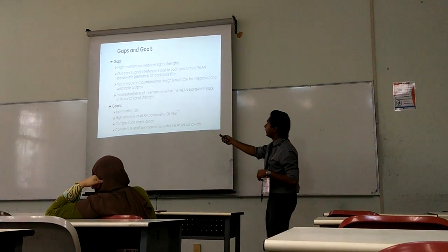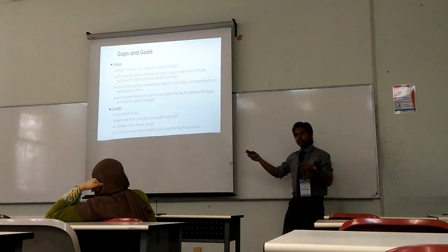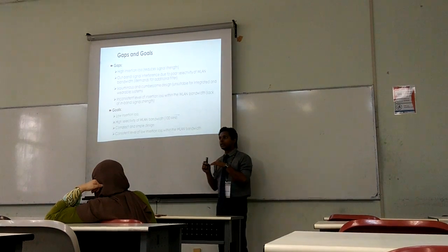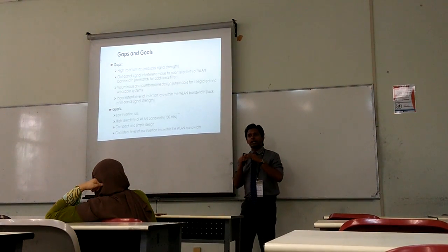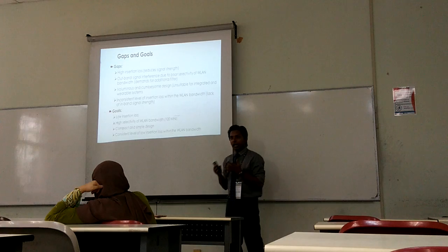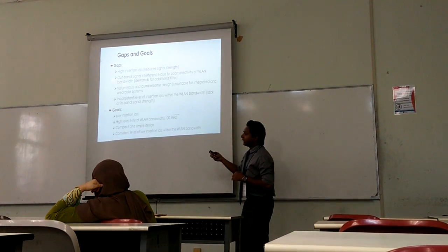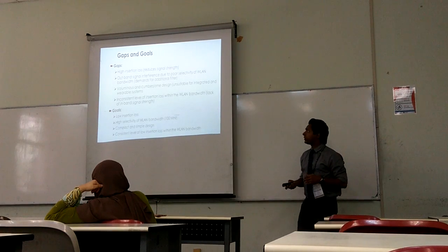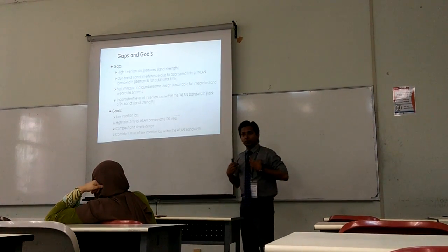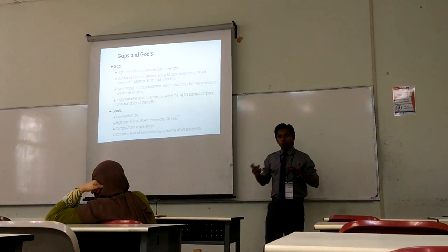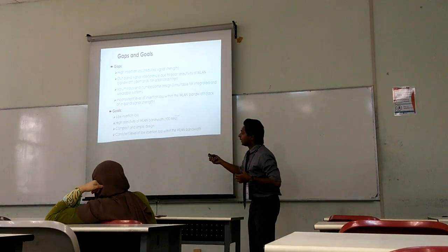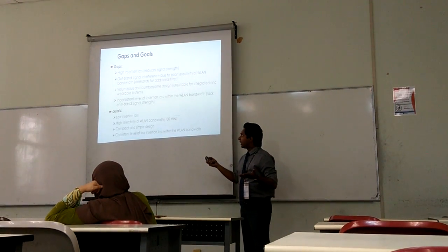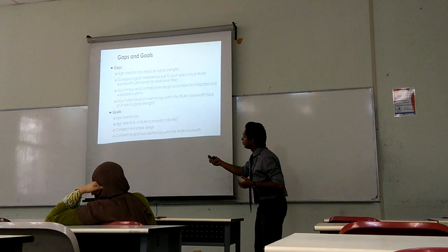Also, the filters are voluminous and cumbersome in design. As I said, the fragmented structure or the defected ground structure are difficult to design and implement. And also, some filters are voluminous, which is unsuitable for integrated systems, or these days, for wearable systems. We are using portable wearable systems, mostly focusing on antennas, but we additionally make use of filters also.